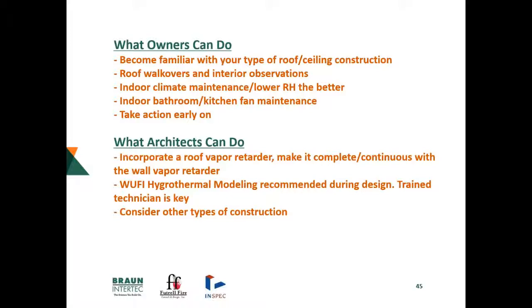That brings up another way to kind of minimize some cost, but you still should probably create that perimeter vapor retarder connection between the wall and the roof. That's still going to be vital even with a compartmentalization type of construction. So that's all I've got, and I'll turn it on over to Scott.